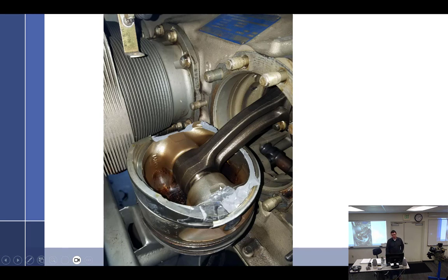So this is fuel injected. It's a little different, but not by much. And so you turn on the boost pump, you have the mixture in, fuel starts running. And in this particular engine, there's a nozzle up top near the induction that just sprays it in there. And so if the intake valve's open, it just starts puddling up inside the cylinder. And then when you hit the starter, it hits that fuel, which is a hydraulic, we call it hydraulic lock.